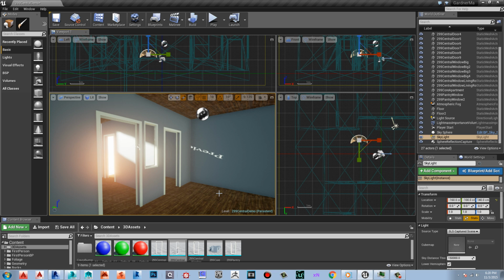So when I made areas to texture with a color map, I made sure that those color maps snapped on a grid the same as my creation of the normal maps on whatever 3D surface I was putting them on. That way the color maps match perfectly with any indents or extrusions of the normal.